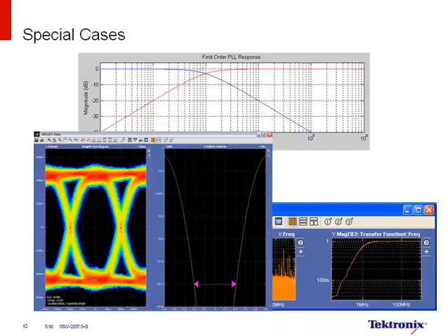Let's think about the root cause of why someone would want to do that. I don't have a picture of a low pass jitter transfer function, but let's think about the root cause here. The reason for a high pass transfer function is because at the low end, the CDR will track and reject the jitter. The reason for a low pass function is that the PLL behaves differently. If you think about a PLL, it's a low pass filter.